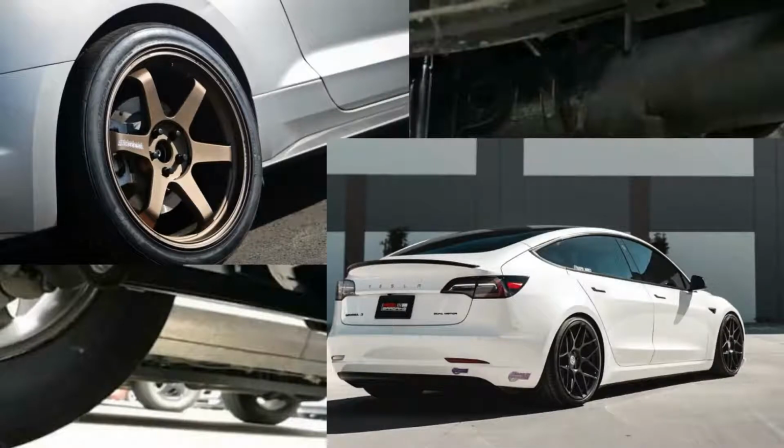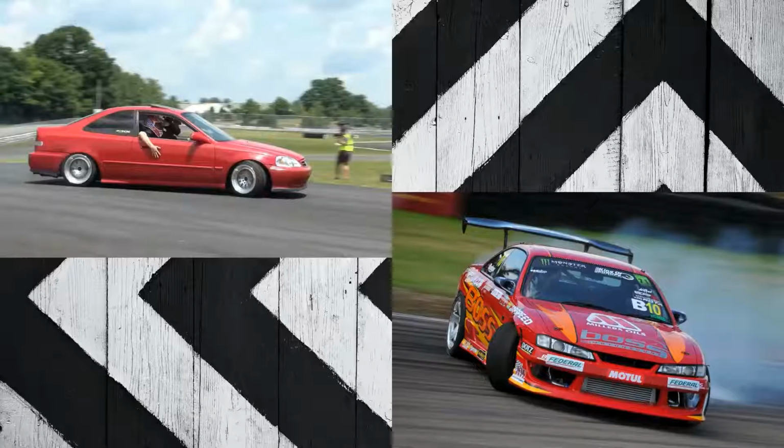And for four-wheel drive cars, LSDs are great for mitigating torque steer while cornering. With so much weight above the wheels in a four-wheel drive car, they can have a tendency to get squirrely under acceleration. An LSD reduces this, preventing the driver from feeling the fun but unsettling shake of the steering wheel.